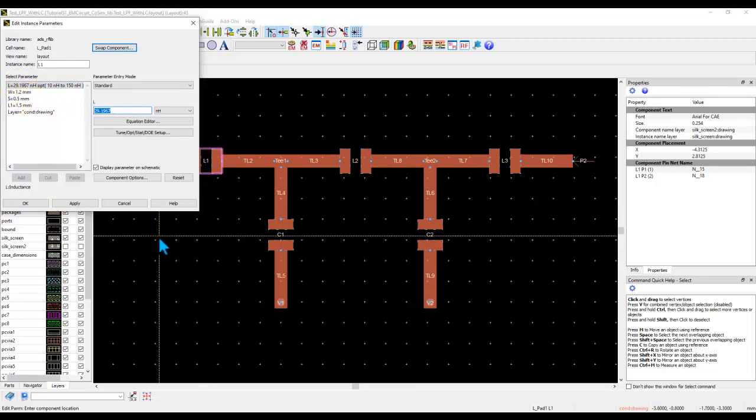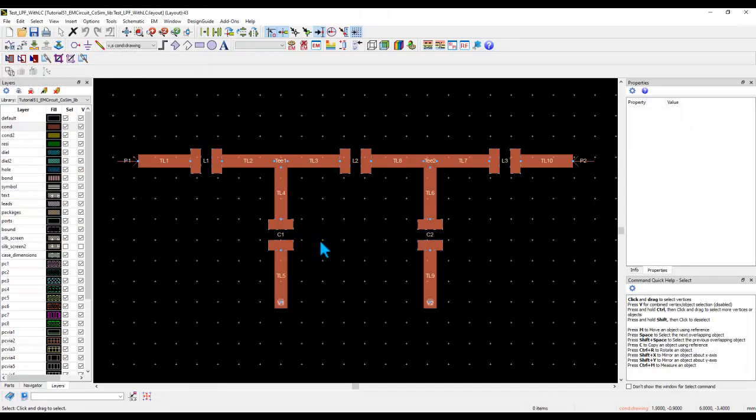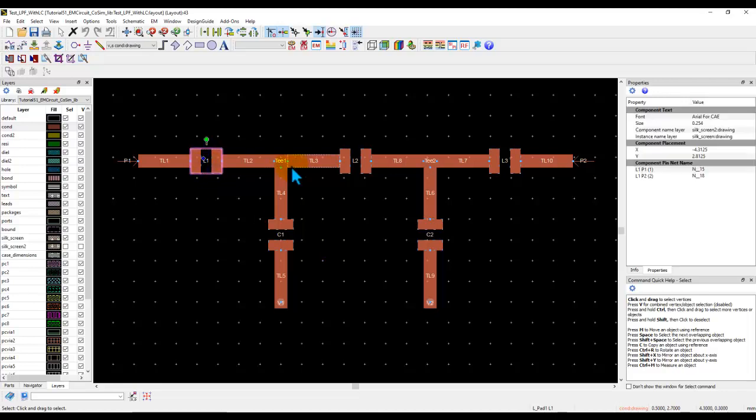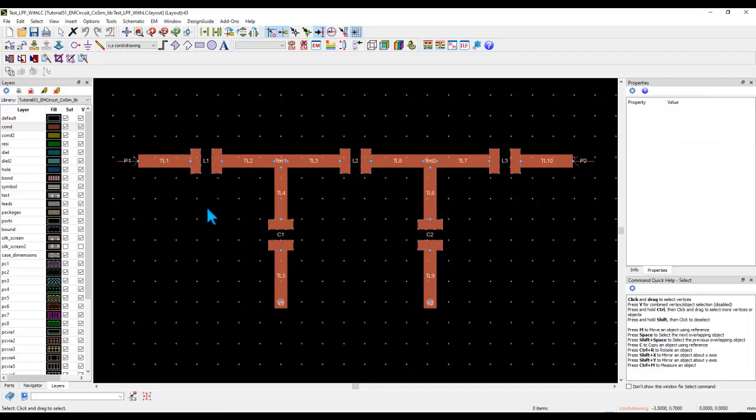All right. Now, if I have to set up an EM simulation or EM circuit co-simulation using the traditional techniques, I will have to delete all these discrete components from my design, and then we insert these pins at the connection points where later we would like to integrate these components in a schematic. Well, that's how the traditional things work. And those are easy things to do if you have very few components.